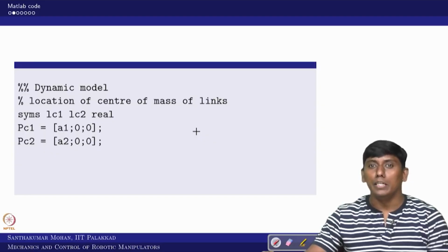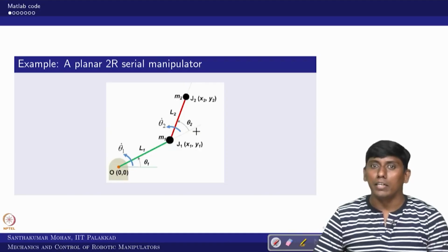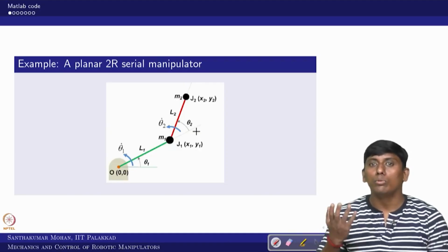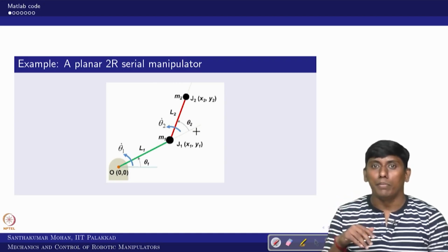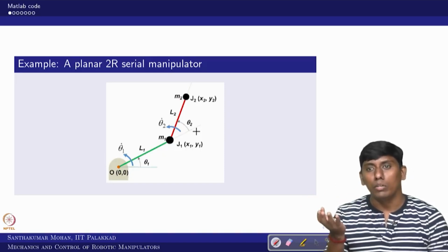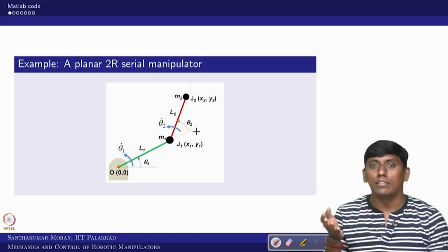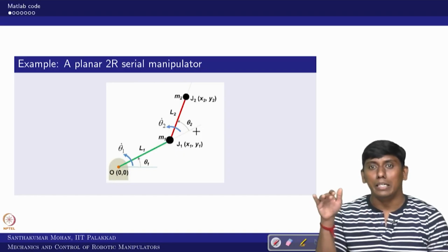First, what we need to know: till now, in velocity kinematics, we have already shown how to derive the DH parameters with the help of frames. Once you obtain the DH parameters, you can substitute them in the Matlab code. You can find the rotation matrices and position vectors of the individual joints.